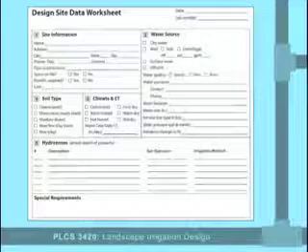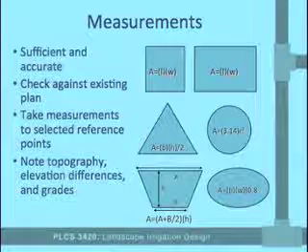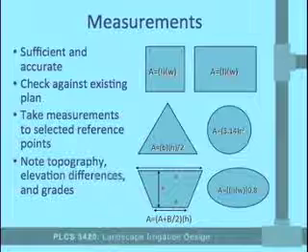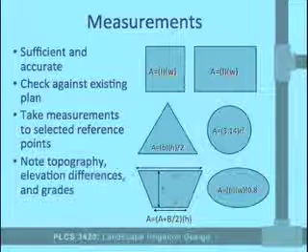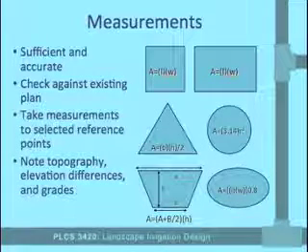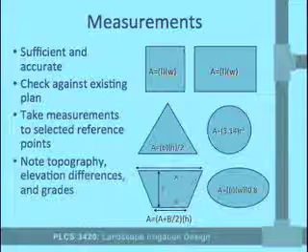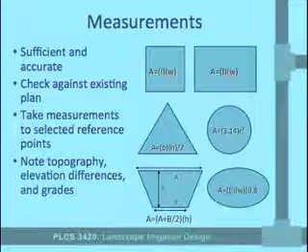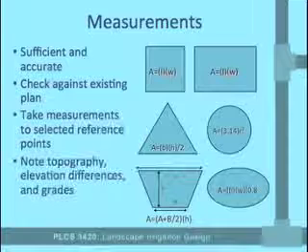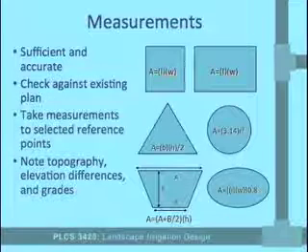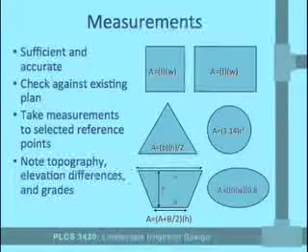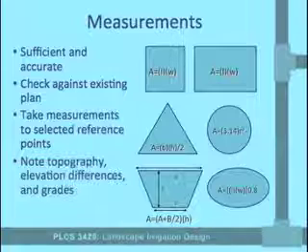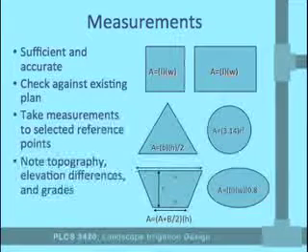Making accurate measurements of the site is critical so that a scale drawing can be made if needed. Now it's not always needed, and I'll talk about that in a minute. But if it is, then you want to be sure that you take a sufficient number of measurements and that those measurements are accurate enough to create the scale drawing. You want to check that against any existing plan you might have to work with.